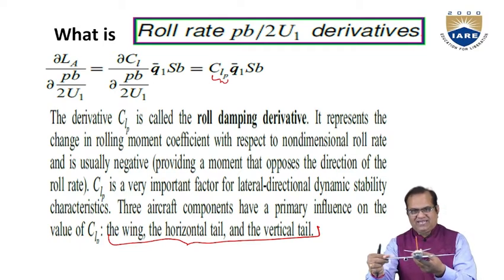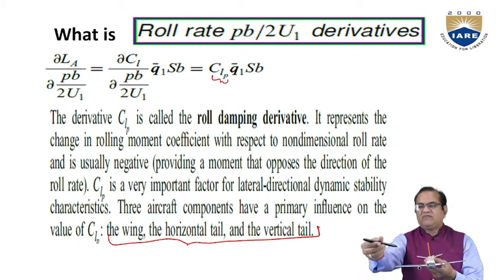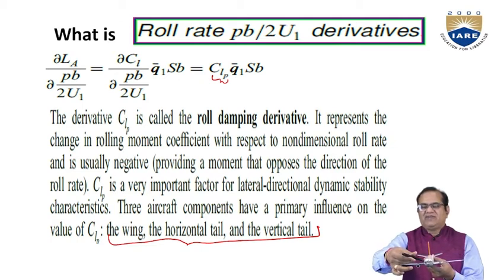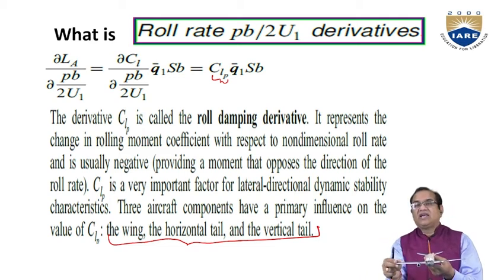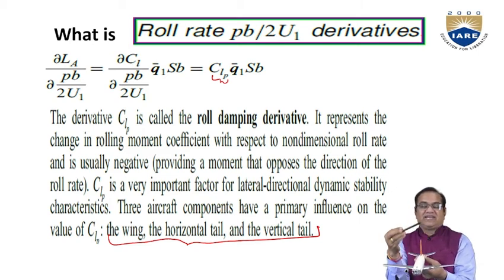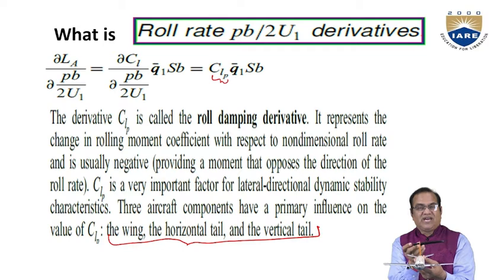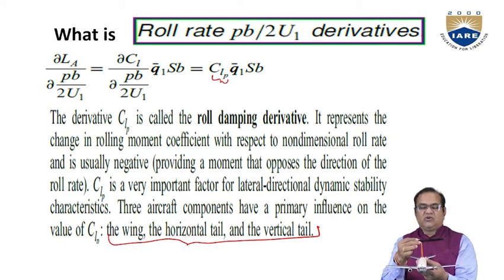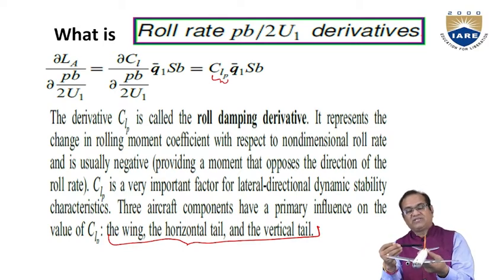So it is going like this, it will drift like this. So a side slip angle beta will be generated here, and this side slip angle will hit the fin and a Y force will act in this direction, the negative direction. This is the positive Y and this is the negative. So in this way, the aerodynamic center is much ahead of the fuselage reference line.